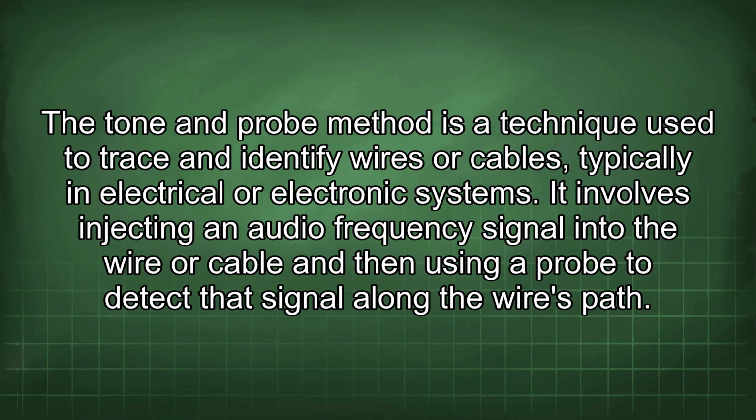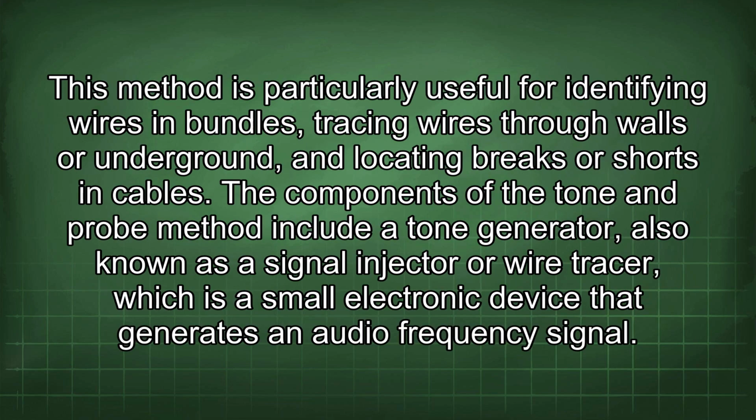The tone and probe method is a technique used to trace and identify wires or cables, typically in electrical or electronic systems. It involves injecting an audio frequency signal into the wire or cable and then using a probe to detect that signal along the wire's path. This method is particularly useful for identifying wires in bundles, tracing wires through walls or underground, and locating breaks or